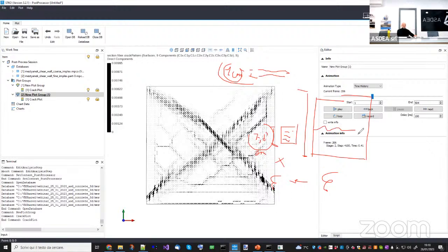Okay, so in reality, I would have a crack, but in the finite element approximation, I will have a smeared deformation, like many, many cracks, such that the deformation here times the length of the element gives me this crack opening. What does it mean? It means that at each integration point of this element, I will have a smaller deformation, so the steel rebars will undergo a smaller plastic deformation. That's why with a very coarse mesh, you don't see that, you see a narrow pinching, okay?